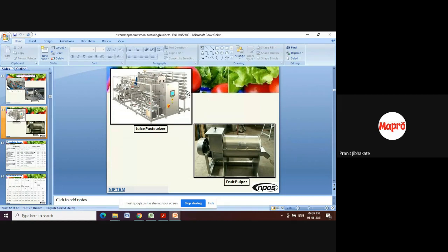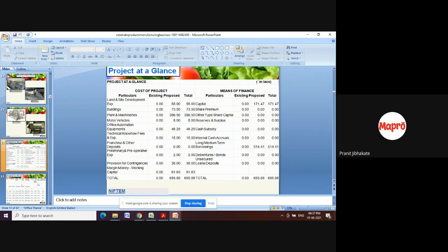Pasteurization, you may all know, I think, what is pasteurization? It is heating for a specific time to a specific temperature, and then immediately cooling it. For our pulp, we are heating it to 93 to 97 degrees Celsius for 33 seconds, and then cooling it down to around 4 degrees Celsius. Okay, so that's how we make pulps.